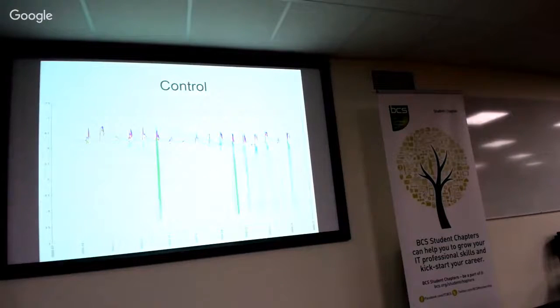This was so that each node could forward data from other nodes. They're transmitting data to each other with radio. If you want to be able to do that effectively, you have to be on for a while every now and again to be able to hear other people transmitting, because when you're asleep, you can't do anything. So if you want to save more power, you have to be more antisocial. You have to be selfish. You turn yourself off for longer periods in order to conserve your battery. So this was a control experiment where it was just on for fixed periods in that 500 millisecond sequence of events over time.